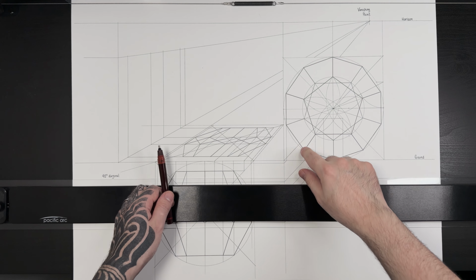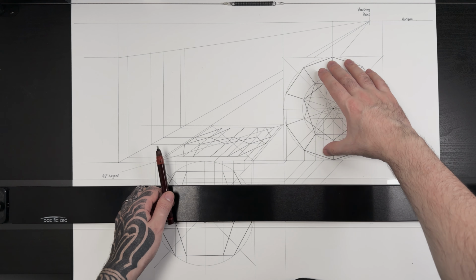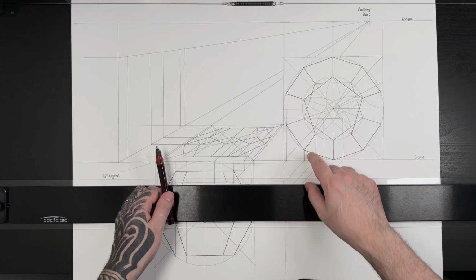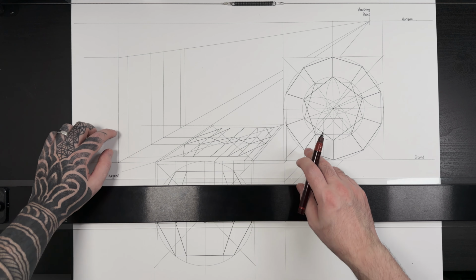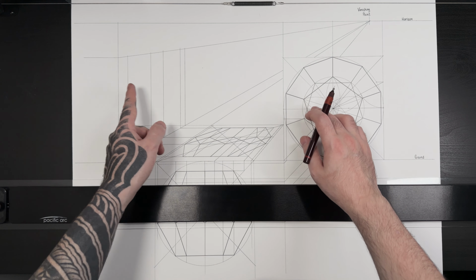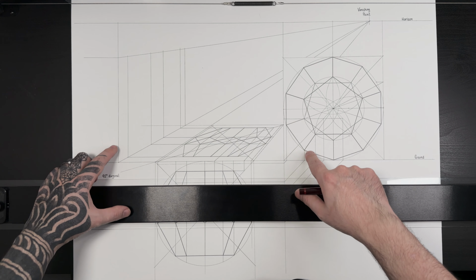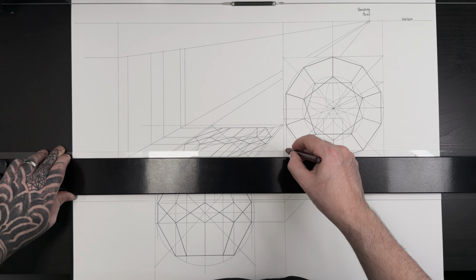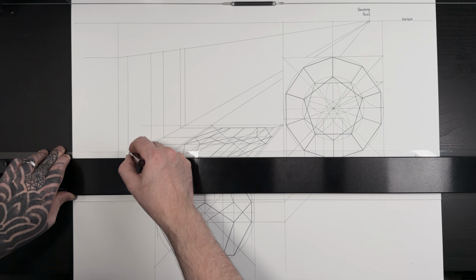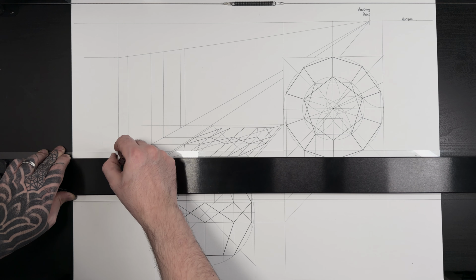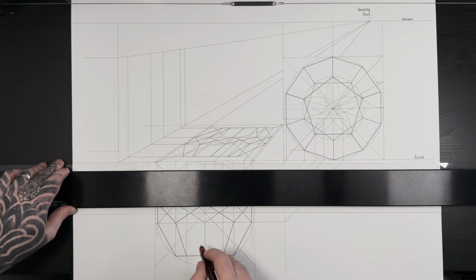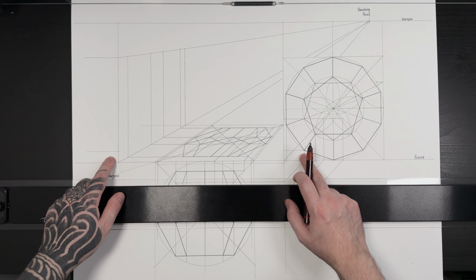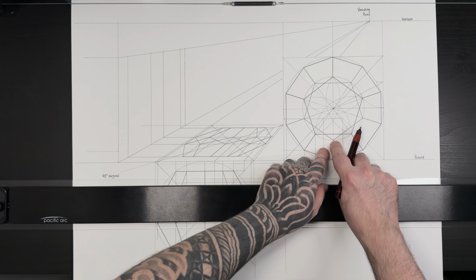Next, we're gonna use many reference points from our front view so that we can use them as reference for the side wall or side view that we're going to have. So I'm gonna start with this corner and then try to follow each corner that I use. And all you have to do is just extend it to the side so then we can project it later.